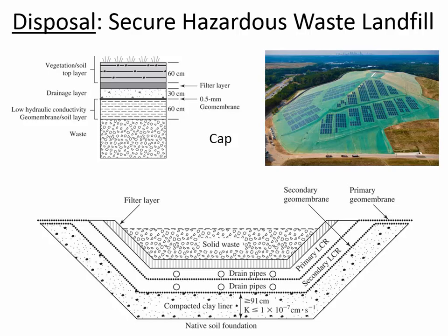It would not be the sort of thing where they say, well, we can just use this secondary drainage pipe as a backup system and continue normal operations. They would actually have to start excavating the landfill and searching for the breach in the liner if they start to detect anything in the secondary drainage layer.